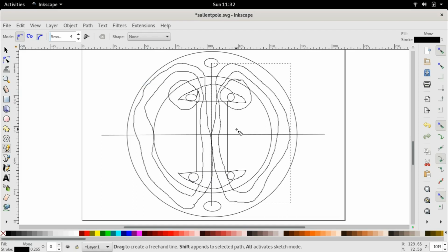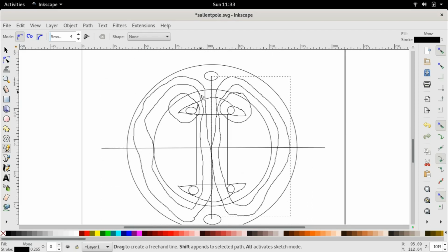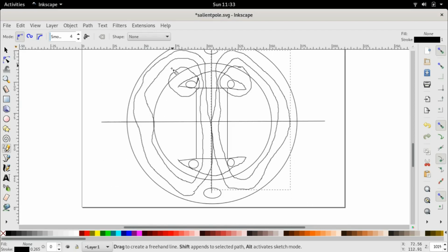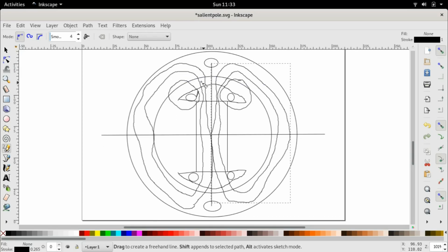So the question here again is, we can do exactly the same calculation that we did for the stator, right? We can determine the strength of these flux paths using the radius, because as always we say the flux always chooses the path of least reluctance, and the path of least reluctance will be the path where this air gap has the smallest length, and the place where this air gap has the smallest length is always along the radius.